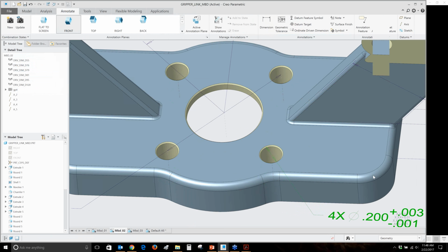And we'll show you again inside here. We're just going to create a basic dimension. We go ahead and select on the surfaces here to create the reference dimension we want to show. Show it on the surface here. A created dimension, same dashboard user interface here. I can put in the text here that it's a reference dimension if I want.